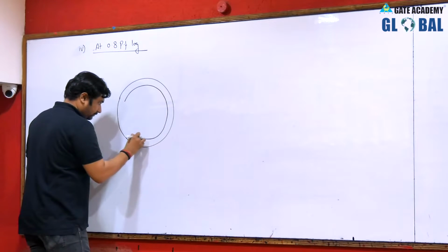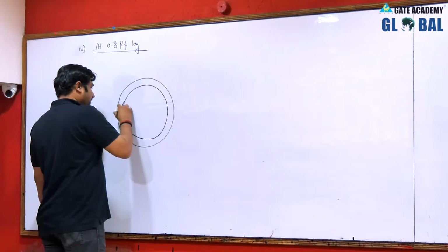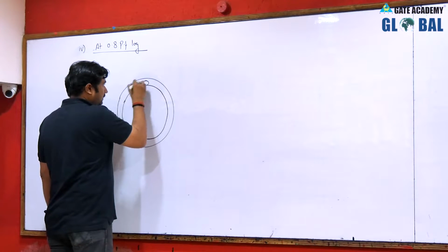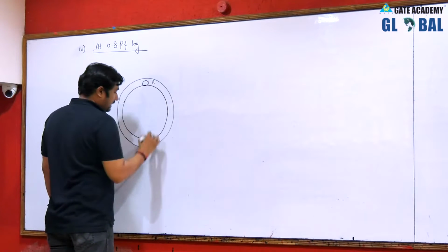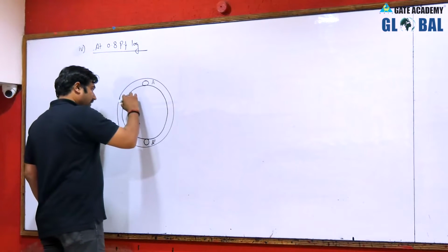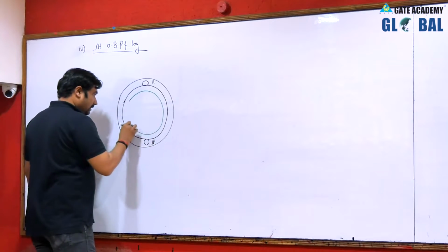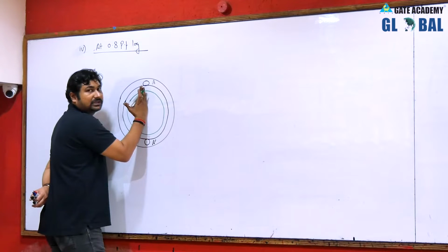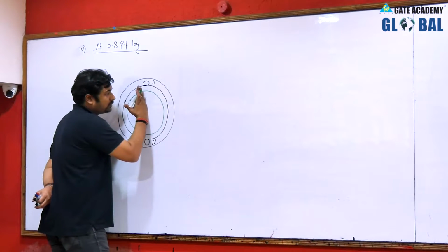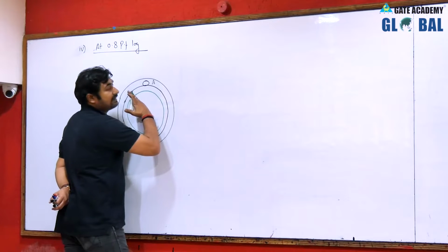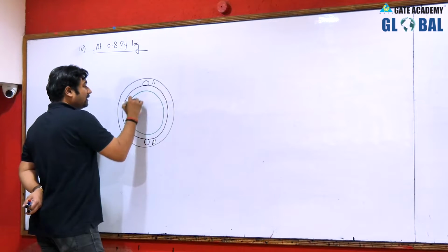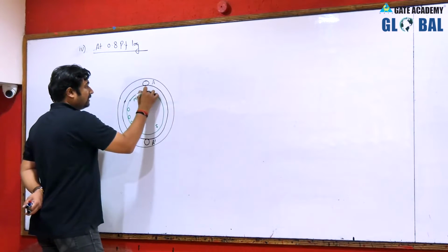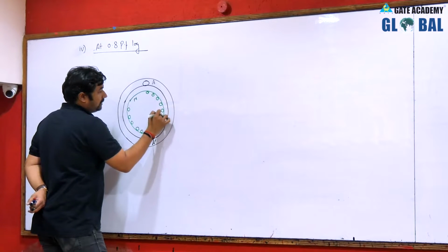Now please see, we have this as an alternator, with stator and stator conductors as A and A dash, and this will be your rotor. Now at 0.8 power factor lag, when the north is at this position, the induced EMF in the A phase will be maximum, but the current flows when the north reaches this point because the current is lagging the voltage. So, when the rotor north and south reach this position, the current flowing in A dash is going to be maximum.